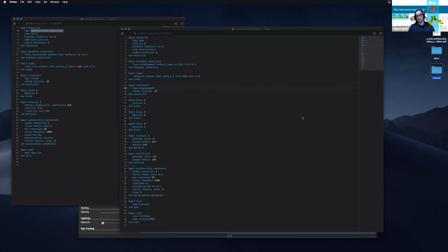One was maximizing the stiffness with a volume constraint. At the re-entrant corner there was a stress concentration. Yeah, I remember. And it didn't remove that stress concentration. It basically kept it there. And then this mass minimization with stress constraint actually smoothed out, rounded that corner and removed the stress concentration.